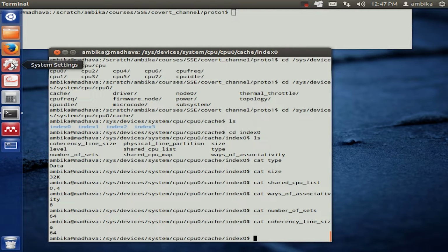Based on all of this information, we can next construct a typical address of such a cache. We mentioned that this cache memory has a cache line size of 64 bytes, which indicates that the lowest 6 bits of the address comprise addressing within the cache line.